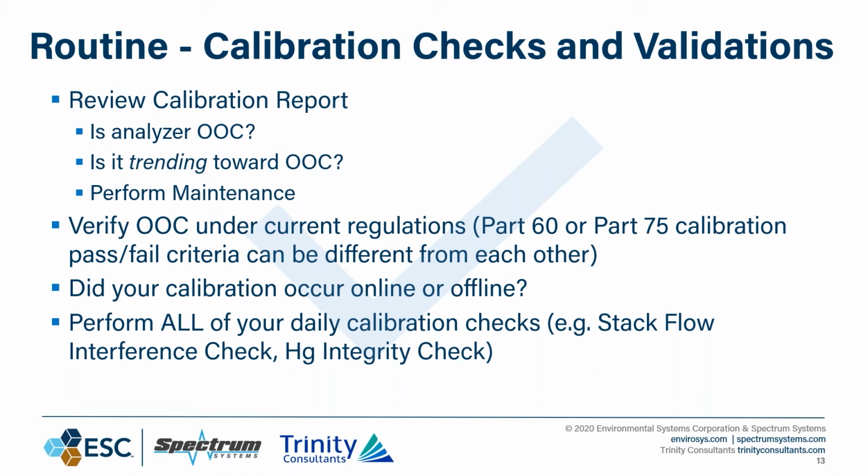Is there a historian, or are they putting in an Excel spreadsheet that shows them that if they're at a certain number, they take action, and don't let it get close to the performance specification? Yes, there are DAS systems out there that will actually offer up a graphical display of calibration trending, a trend history report. It will actually demonstrate what your cals have looked like over a defined period. So you can actually see if you're inching up or inching down towards pass/fail, towards failure